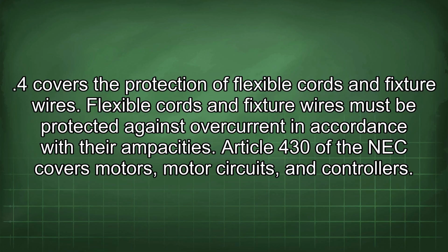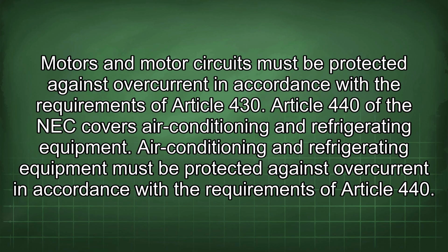Article 430 of the NEC covers motors, motor circuits, and controllers. Motors and motor circuits must be protected against overcurrent in accordance with the requirements of Article 430. Article 440 of the NEC covers air conditioning and refrigerating equipment. Air conditioning and refrigerating equipment must be protected against overcurrent in accordance with the requirements of Article 440.